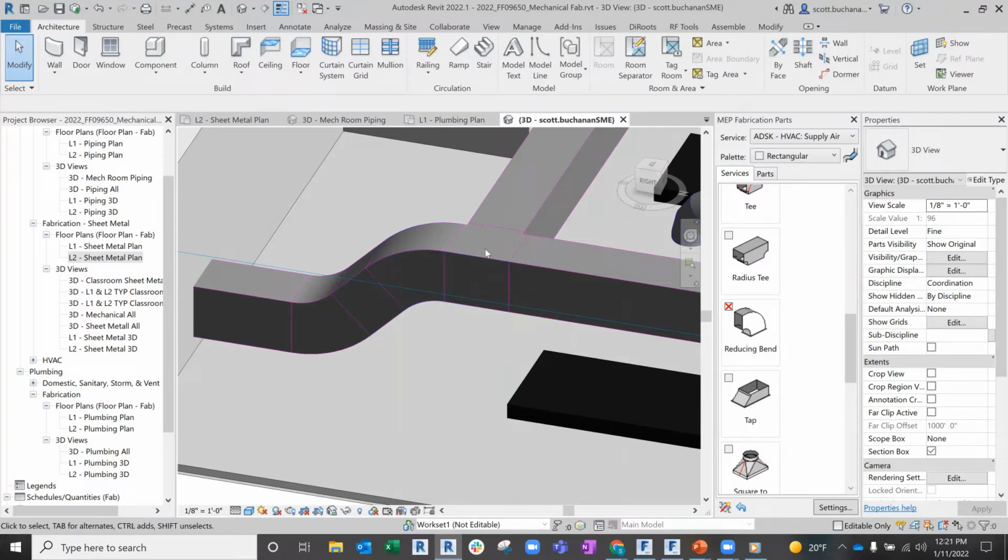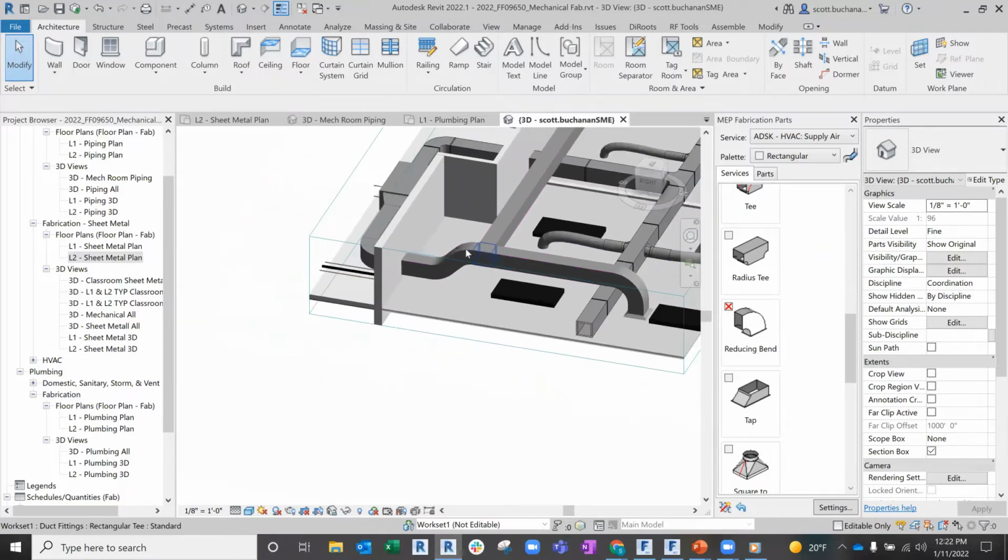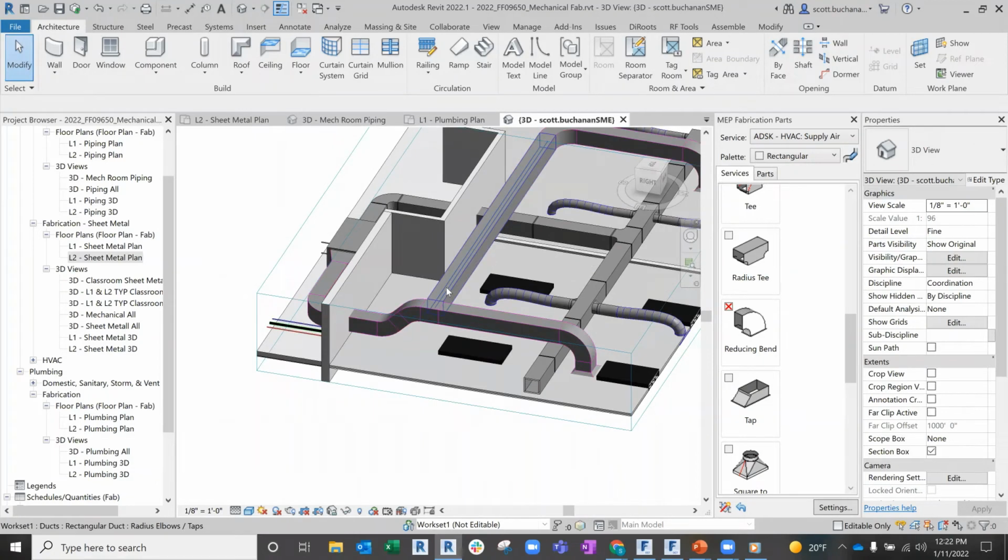Okay, it does its best to keep what's there, but if it can't fit, it will not convert it. And so same thing would happen if we were doing some piping and you drop down and maybe we're using a generic fitting and then quickly went flat again. If there's not enough room for the real fitting, it skips over it. So that's what we'll actually see happen with this one here when I do the conversion.